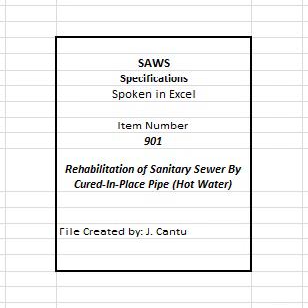8. Point repairs and obstruction removal. A. SAWS shall be notified and shall approve any point repair or obstruction removal before it is constructed. Point repairs and obstruction removals shall conform to specification item number 1103, point repairs and obstruction removals. 9. Pipe leakage control. A. Contractor shall stop infiltration or leakage into the existing pipeline to prevent contamination of resin in liner.